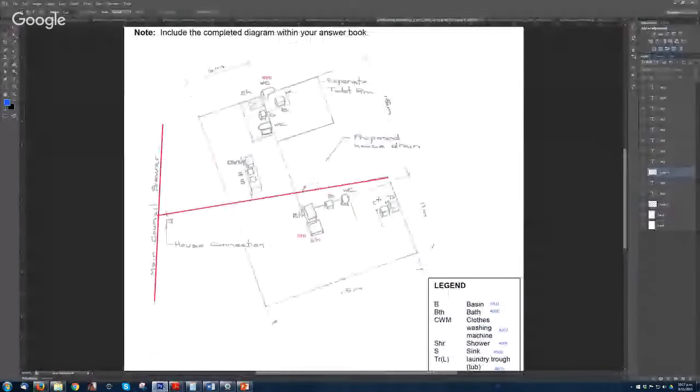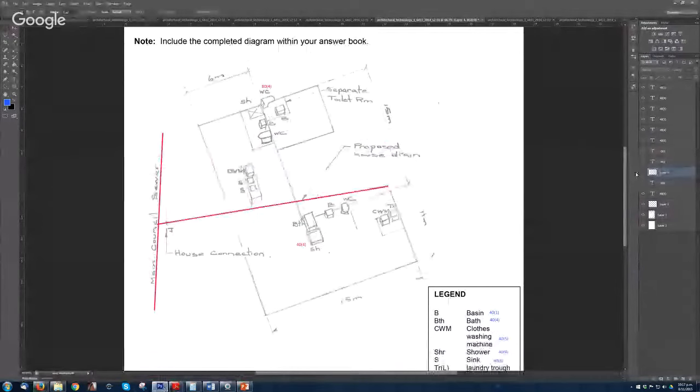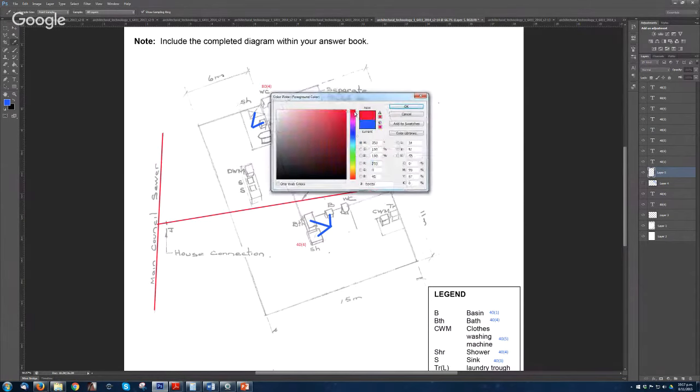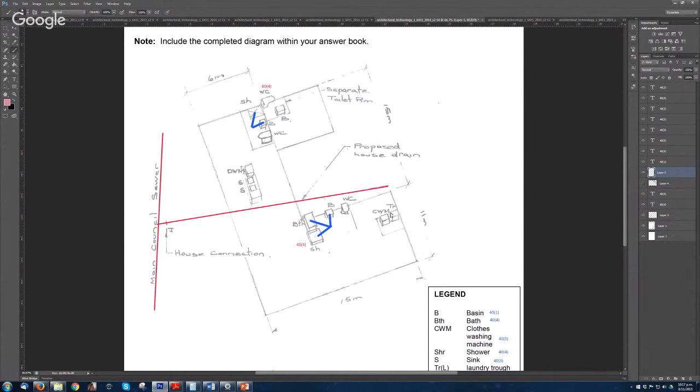Okay. So we had a floor waste gully here. Connect the shower to that basin. Shower, basin, bath, basin, and you never connect the WC to that. Always have this on its own line. So now I'm going to connect those two here.